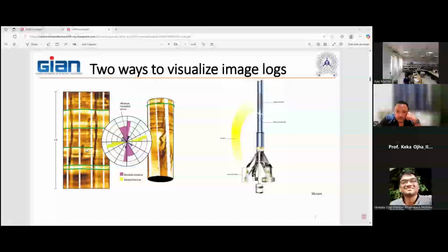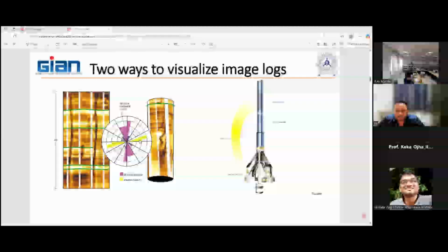In the wellbore, this is the direction of what? The minimum horizontal stress. So the Rose diagrams indicate the direction of the breakouts and drilling induced tensile fractures. This is the simplest representation of this. So what do you think is the direction in this area? What is the direction of the SH max according to this figure?